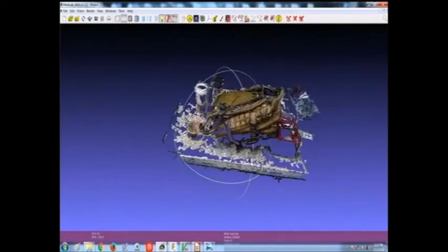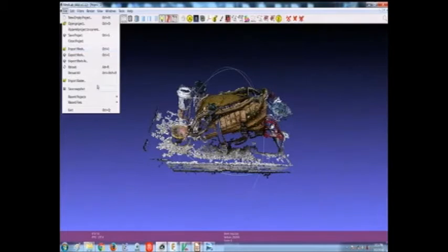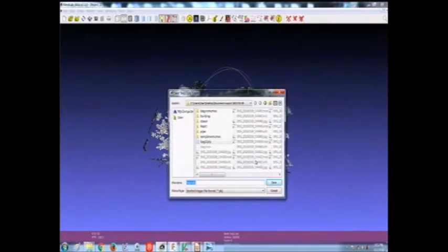And I believe that's good enough. So one thing about Meshlab, it's a little glitchy, right? It's free, it's open source, so you can't expect it to be perfect. So one very important lesson is save early and save often. It's also a destructive process, so there is no such thing as the back button. FYI, save at every step and you'll be much happier at the end, because I get a few glitches here and there every now and then.